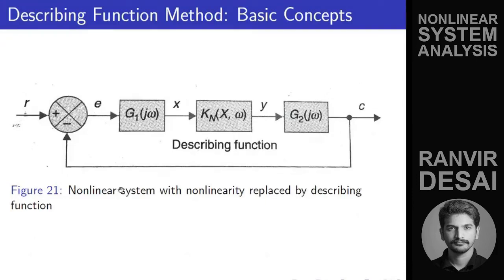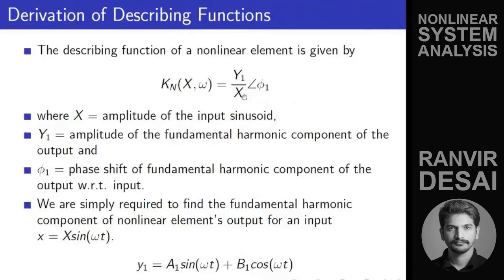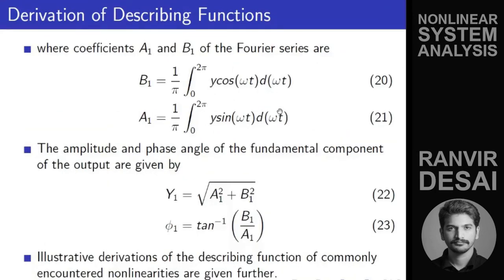This whole thing is taken into the Laplace domain. So this en was replaced by this describing function. As you can see, this is nothing but output upon input, so the gain of that function and phase of that function. Basically that nonlinearity is converted to a counterpart or a replacement which has a similar frequency response. But we will not go into this method much.